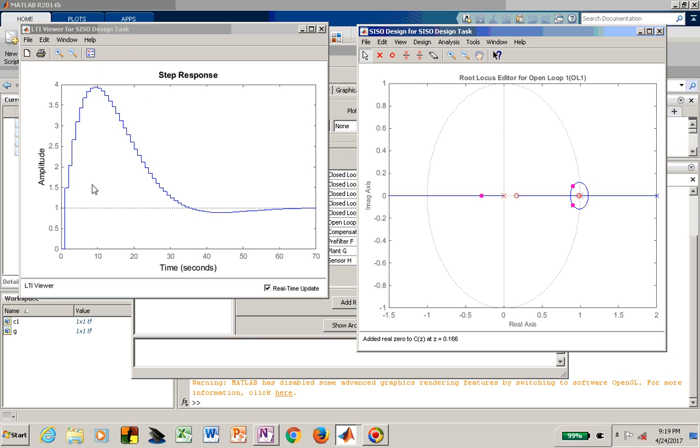We have a stable system, and with all of these magenta circles, we now have 3 closed loop poles. The 2 pole branches between 1 and 2 meet and circle around again because we had that zero at 0.9833, and for this particular choice of gain, we still have this pole inside the unit circle and our 2 complex conjugate poles. Now, ideally, if I could grab that zero,